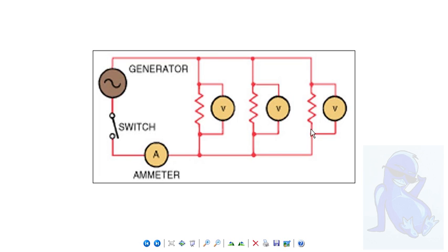Voltage is a measurement of the electromotive force or the electrical pressure, and in order to read that pressure, you need to have resistance between your two leads, or you need to have the line open. So if you measure across an open switch, you can measure the voltage, because that's a measure of the electrical pressure. If you measure across a working load, you can measure the voltage. The amperage has to be measured in series while the current is flowing, while the electrons are flowing.